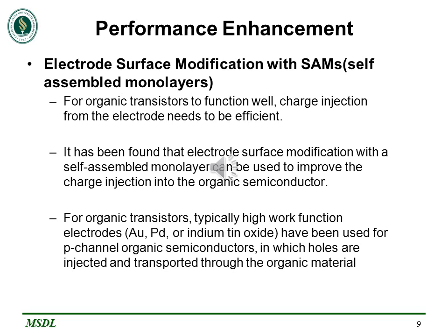So after the fabrication steps, we come across the problem of performance enhancement of these thin film transistors. Basically, the key performance issues for thin film transistors are large carrier mobilities and high on-off ratios for high-speed operation and low energy consumptions. These are the major things that we need to achieve if we want to enhance the performance of flexible thin film transistors.